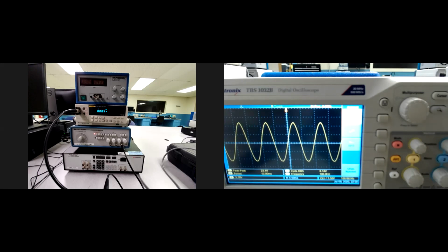You're gonna be able to have the oscilloscope calculate different parameters for you. Okay. So at this point, the first two numbers that we wrote down, those were coming from the multimeter. And please make a note on that. So it was 114 hertz read from the multimeter and 8.08 volts RMS. Make a note that those values are coming from the multimeter, because all the signals that we're gonna be generating, we need to make the distinction between them.